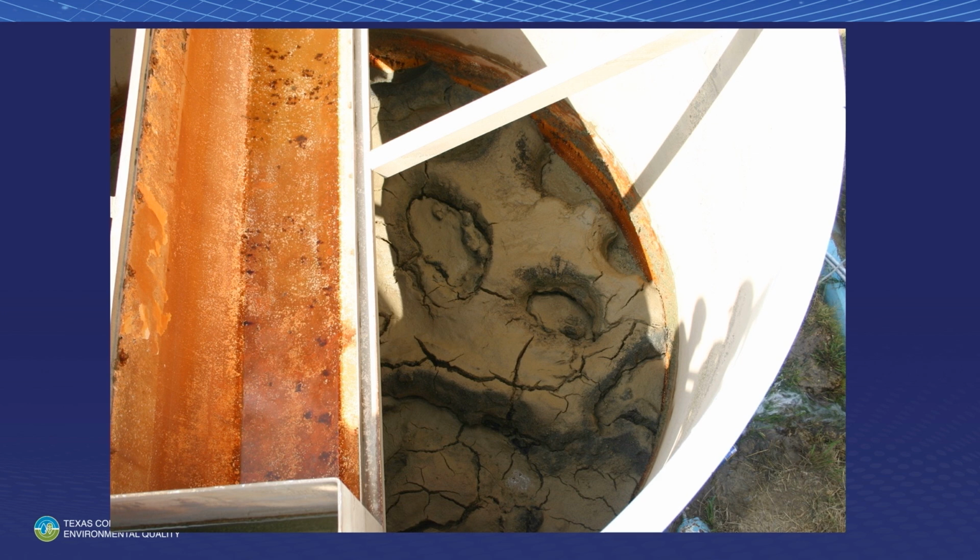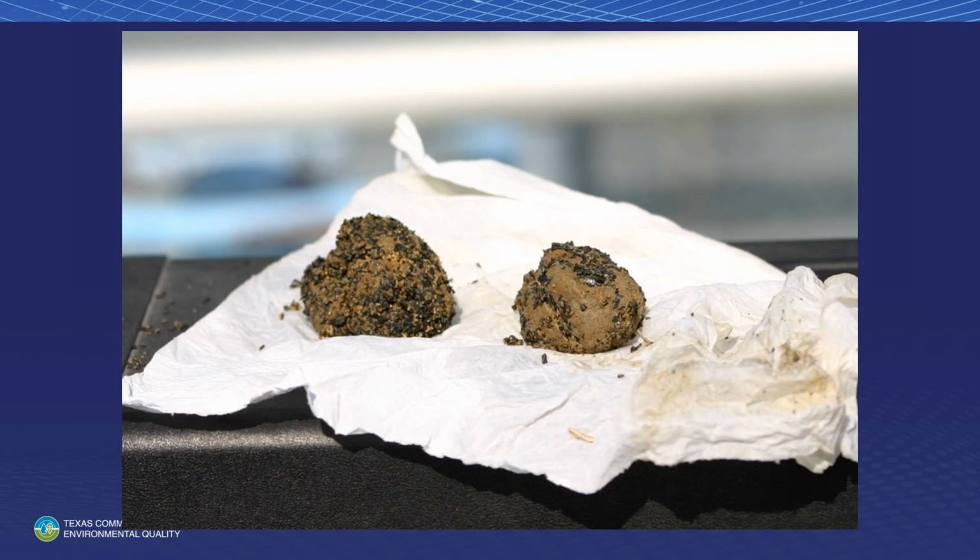It was huge. When we did get to where we could dig down in it, we found things like that down in the gravel. I don't know whether he could backwash, but the backwash water was just coming up through the holes. It wasn't lifting anything out of that filter at all. I don't think he had really had much training on what it should look like. He was just doing it the way that Billy Bob did it before he was on site. So all the training he had was from another operator that didn't know much about what was going on to begin with, and that had just been perpetuated. But that was the kind of thing that we found in that particular situation.